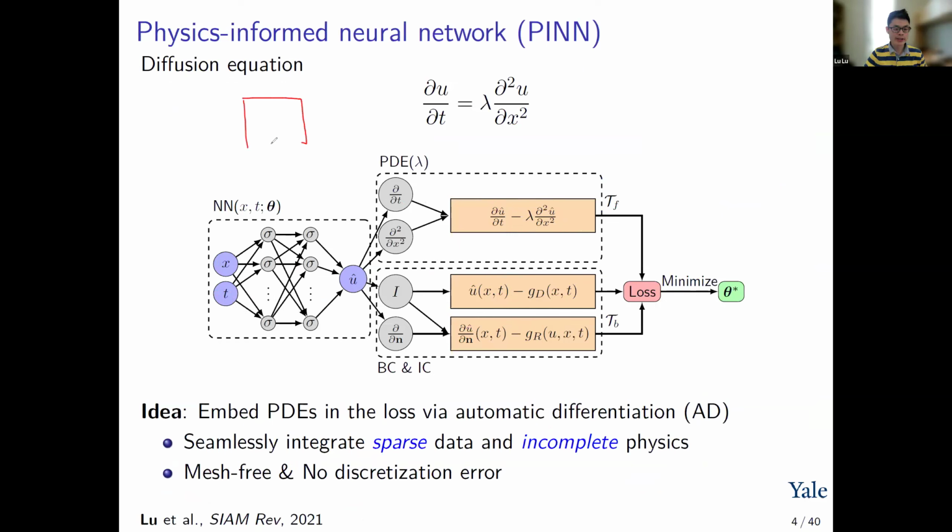If my domain is a 2D square with x, y, and I sample roughly 100 points on the boundary, then if we consider a uniform mesh, we need 10,000 points inside. We can use this as a guideline to select the number of training points. But actually, in 2D we can use fewer than 10,000 points for PINN training. There's no need to use 10,000, but this rough number can be used as an initial starting point.